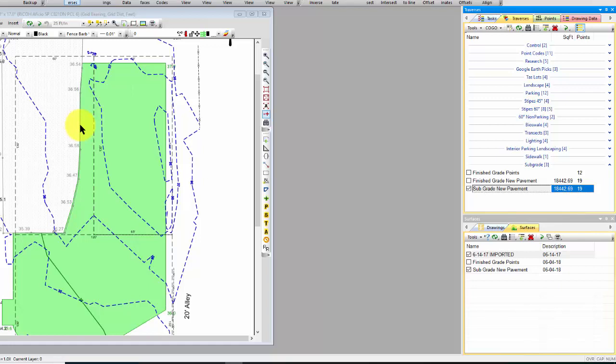And in fact, it creates prismoids that are triangles top to bottom, but they've got their own angles to the surface, in this case between the existing surface at one end and the subgrade surface at the other end. So I just call those a prismoid. Traverse PC can sometimes compute thousands and thousands of those to exactly pick up every piece between those two surfaces. Of course, you don't see all that as a user.